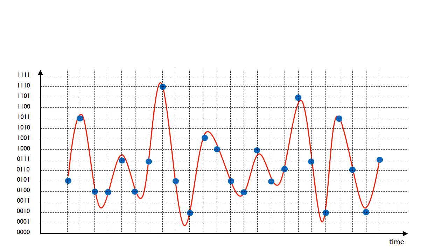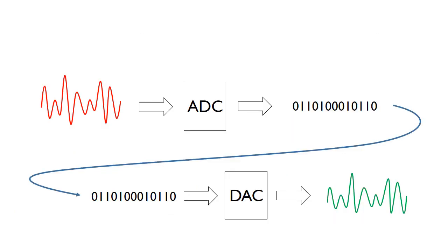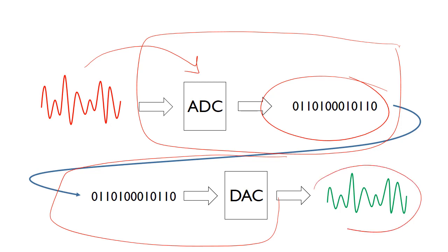So we know for an analog signal, for example, we could have a digital representation of a signal, then output it, convert it back into an analog signal using a DAC. So you've got some original analog signal, goes into an A to D, is converted into this digital representation, which is then transmitted. So this will be the kind of receiver, if you will. Sorry, the transmitter and receiver have a DAC on it. So we get that digital signal and convert it back to an audio signal, which they can output through a speaker or whatever.